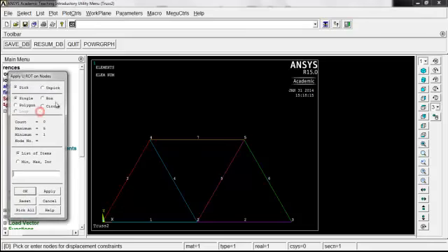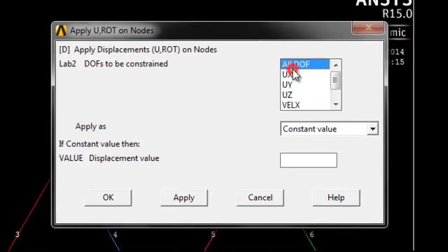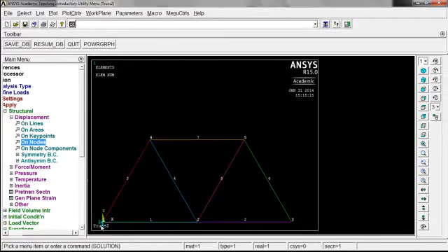All right, so come back here, and we'll select at this point, and we'll say OK, and we'll do all degrees of freedom are fixed, and therefore the constant value, displacement value, is going to be 0. So again, make sure you just select this. You get a blue there. Click on OK, and you get the 2 blue arrows indicating what the boundary conditions are there.